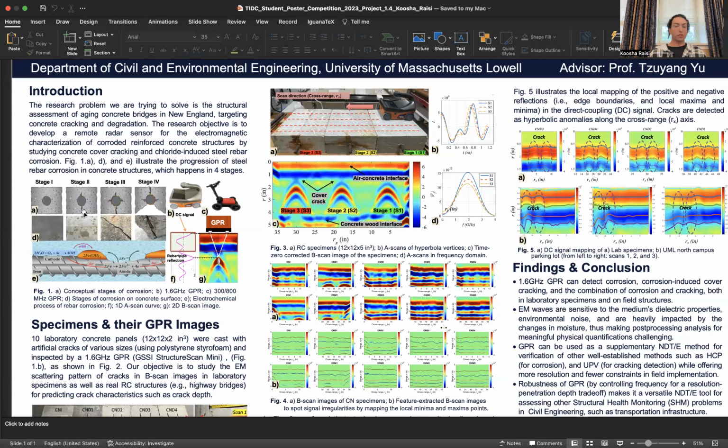When rust is formed, it is typically around 6% more expansive than iron itself. Therefore, it causes stress, and stress in concrete is a problem, because that stress is going to distort the balance of stress distribution in our concrete matrix or medium.